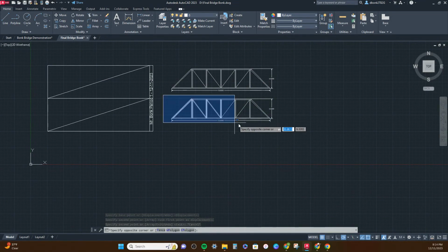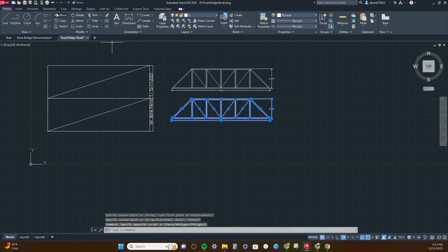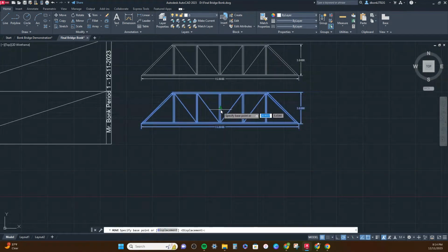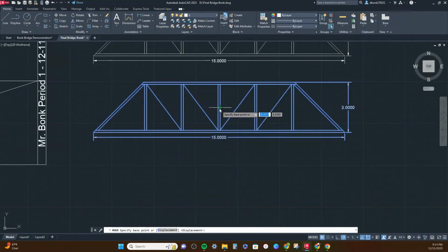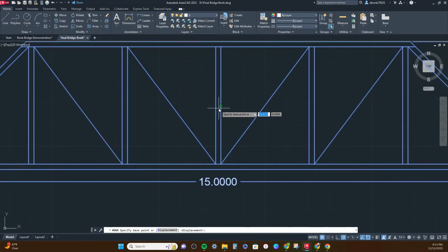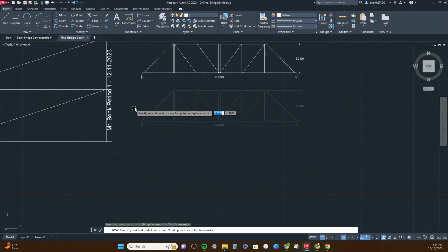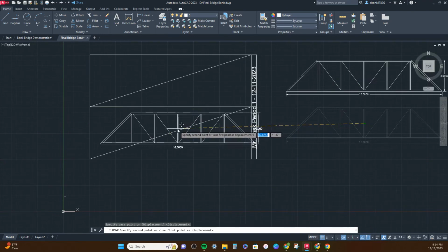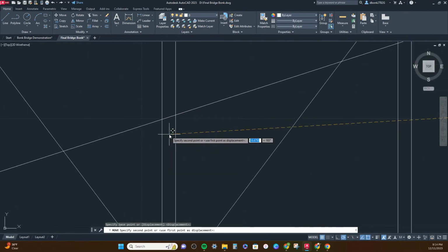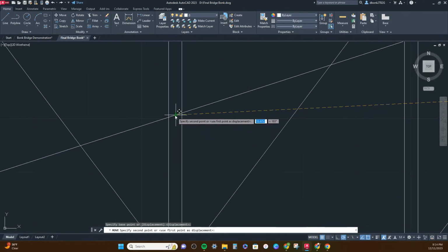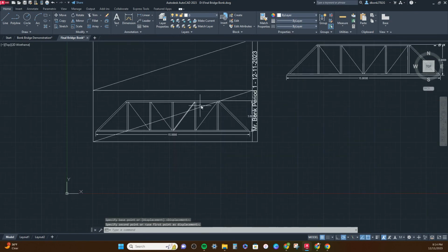Click on one side of it, let go, click on the other side of it, hit move, grab it. That's to grab it from the midpoint of this thing. If it's off by a 16th of an inch or whatever, because you grab it by one of these sides, it's really not a big deal. But if you see that white X, that means you're in the very, very center. Then when you go over this diagonal, you want to make sure that X sits on top of the triangle like that. You click and place it. That'll land it in exactly the middle. Click on that line, hit delete, gets rid of that.